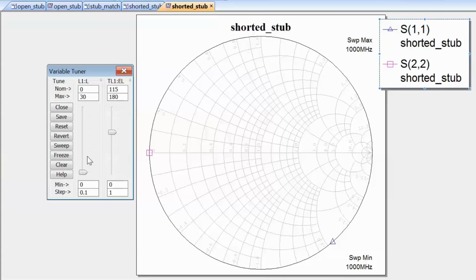So the big difference here, as before, is that when you have a transmission line, either short-circuited or open-circuited, to represent either a capacitor or an inductor, whereas the impedance of the capacitor will always be in the bottom half of the chart, and that of the inductor always in the top half, when you're using an open-circuited or short-circuited stub, depending on the electrical length that you're using for them, you could have either an inductor or a capacitor. However, the usual way things are done is to keep the transmission line length to less than 90 degrees and use an open-circuited stub to create a capacitor and a short-circuited stub to create an inductor.